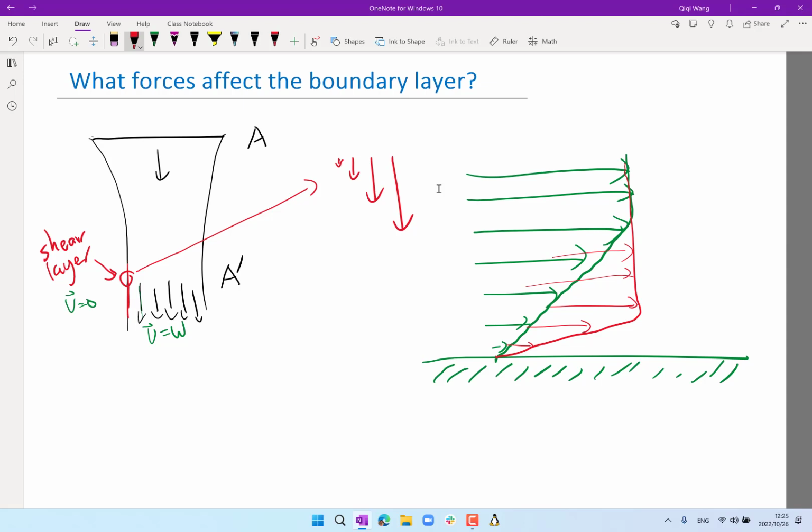And what is the consequence of shrinking, if you think of a pressure gradient along the direction of the boundary layer? Yes, it accelerates the flow, so the pressure is high upstream and low downstream. That's exactly what you need to shrink the boundary layer.